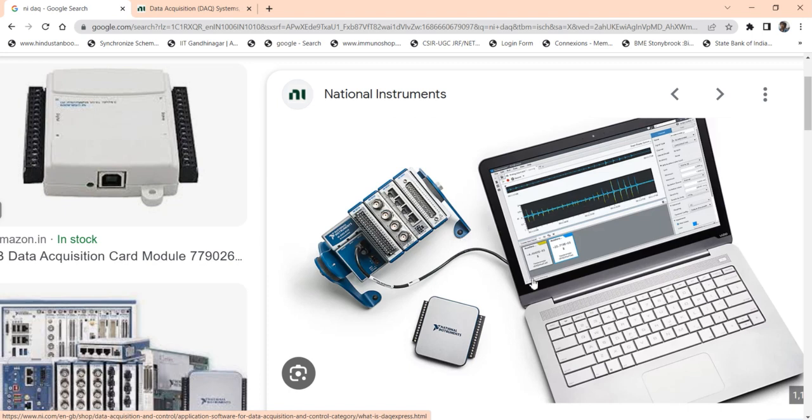Suppose you have 10 different kinds of sensors. One sensor can measure the pH of water, blood and others. One can measure only alcohol. One can measure only vibration. One can measure only temperature. But each and every sensor generates the data in terms of voltage only. So you need a voltage input module. We have this kind of multifunction voltage input modules, so you can utilize them.